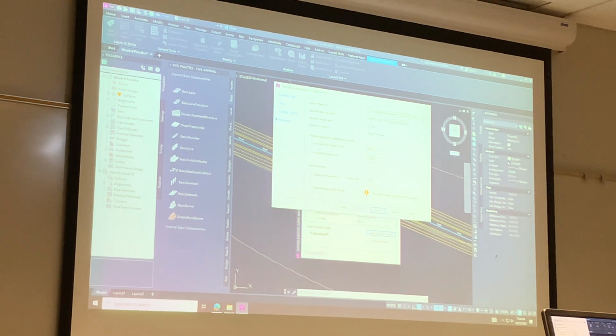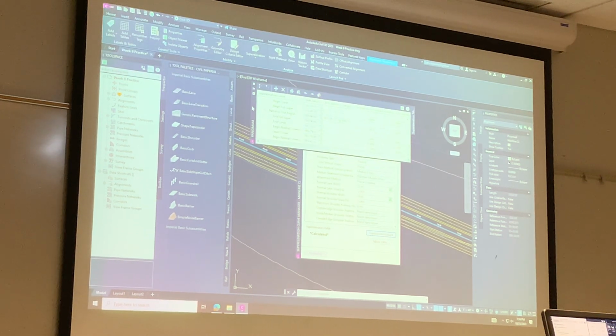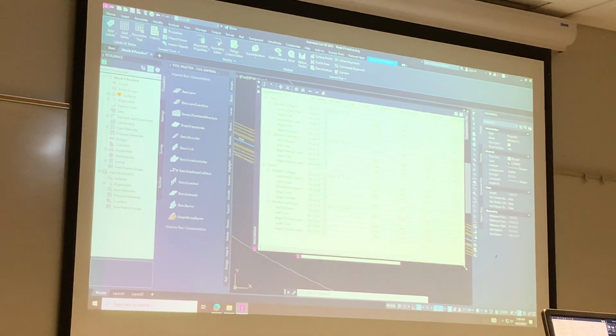Right, and then two-thirds of the super elevation runoff will be on the tangent, which is what we want. So we can click Finish. And this time it didn't give us all those errors, because we didn't use any sub-assemblies that don't accept super elevation or that have trouble with it. You may remember from last week that we got a 5.2% super elevation rate. It's giving us the same here because it's the same geometric configuration.